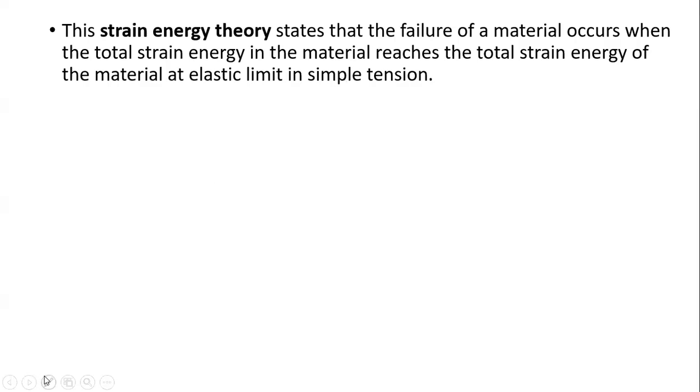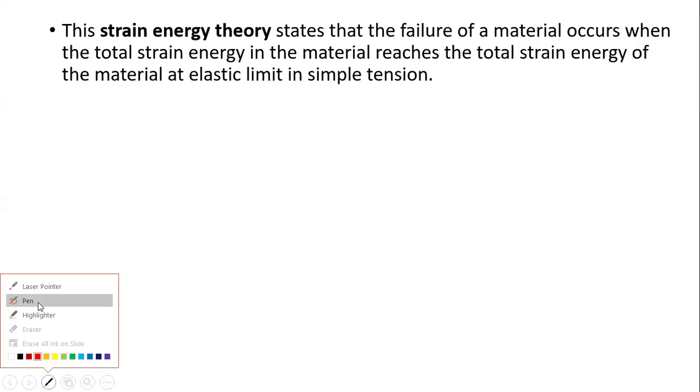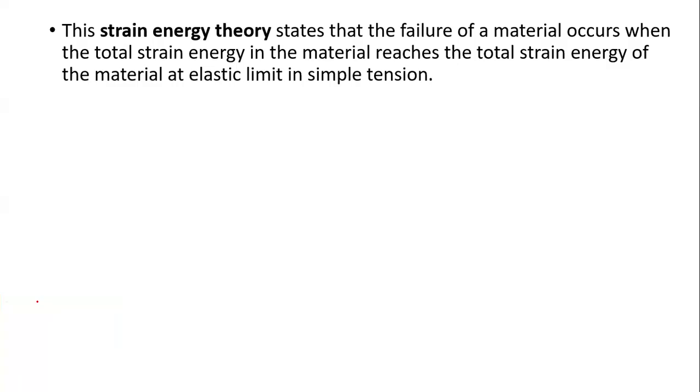In other words, we're saying that a material can fail if the amount of strain energy it's going to have is equal to that strain energy that it has when it reaches the elastic limit, or when it is at the elastic limit, for a material that is being loaded in simple tension. That is what this one states.